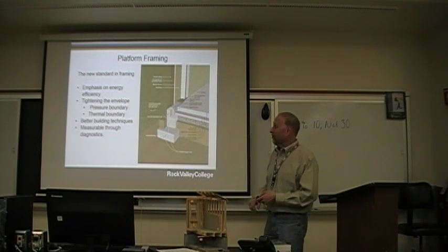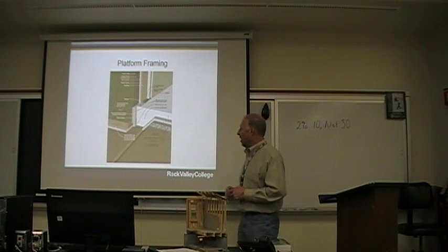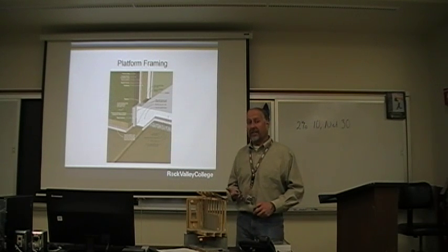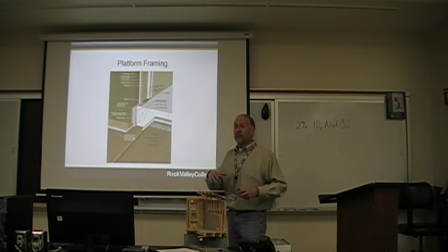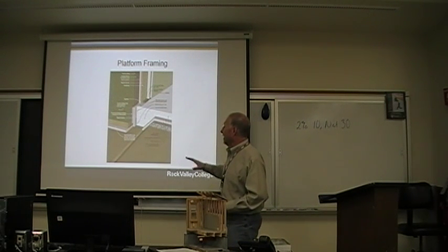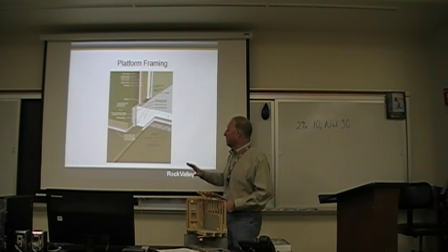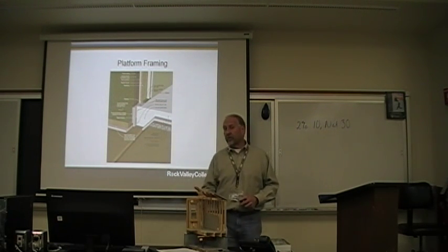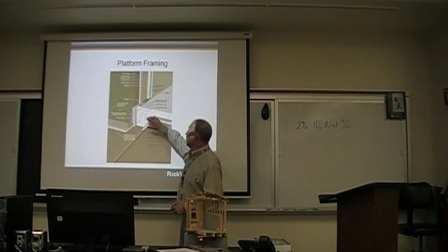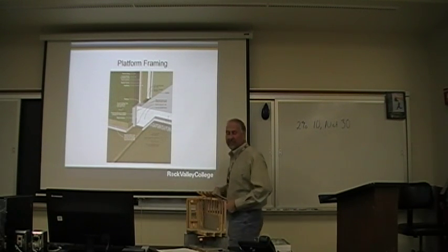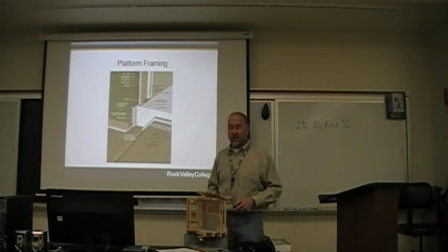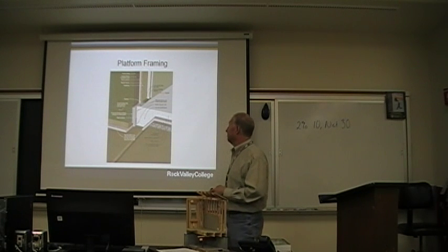So here's an example on a standard foundation. Here I also have an example of what you would see on that grade beam that we saw when we were looking at that typical wall section with the 2x4, the traditional platform framing. We're moving away from that, folks. We're moving away. It's going into energy efficiency. It may not be great extremes. All depends what the homeowner is willing to pay for it. But now we have to be code compliant on certain areas of this. So now we're going to look more at 2x6 construction. We're going to be sealing the holes better. Our insulation requirements are going to be greater. So those are all things we're going to discuss. Right now we're concentrating on framing.